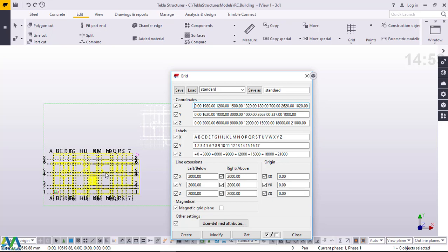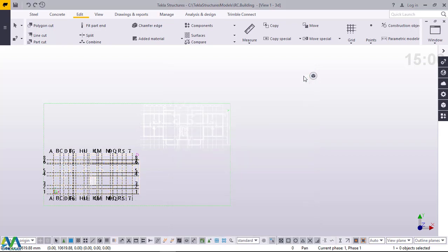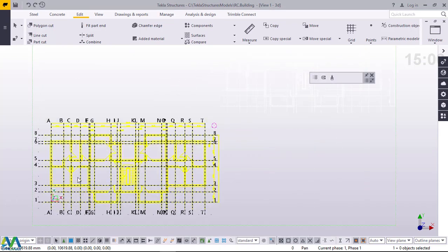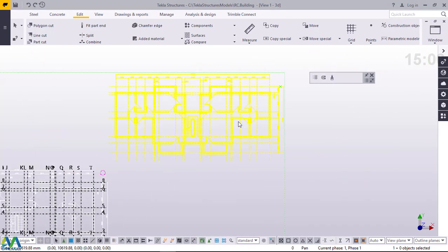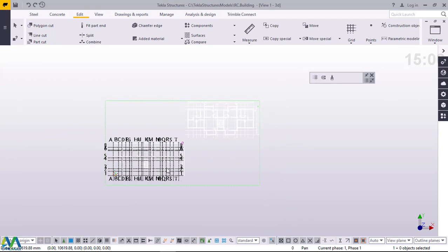That's all about setting out the grid lines and importing the PDF drawing plan for any architectural drawings, and converting the scale to match 1-to-1 scale. Now we are going straight to start placing our columns, pad footings and plinth beams. Now I'll go straight away and close this. I just wanted to show you how I arrived here, and I've demonstrated that clearly. Now this we will delete because we are going to work to this, because it is actually similar to what we are doing.